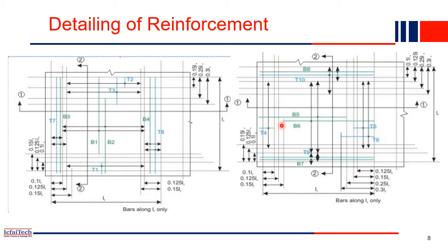You can understand that these top reinforcements are always at the edge of the slab or corner of the slab, because negative bending moments are developed always at the edge of the slab. Okay, now you understood this one. So total, like that, total 18 reinforcements normally we have to provide in the corner. So total B1, B2, B3, like the total B8. So total 8, and near to the corner also. If you see these corners, at the corner we have to provide both, right, bottom and the top. So corner B7, B8, bottom reinforcement.